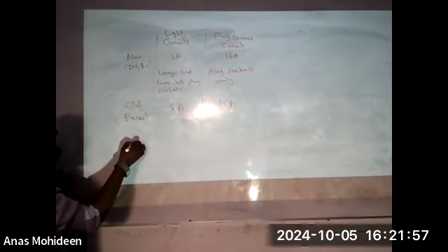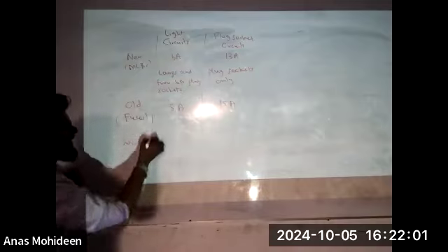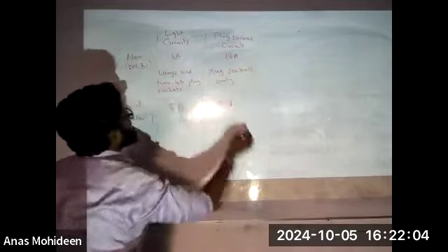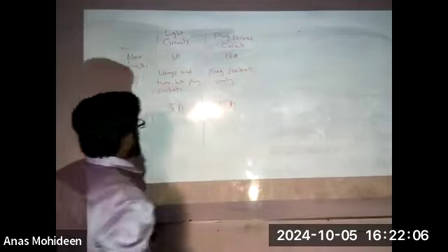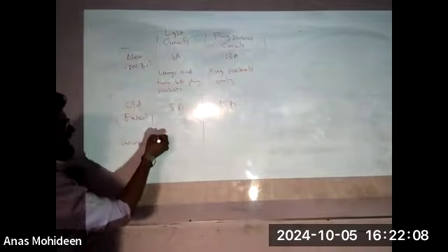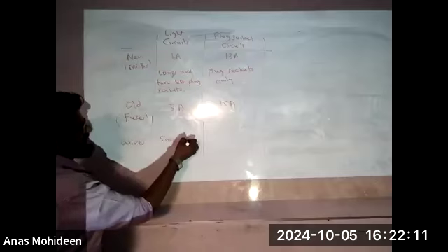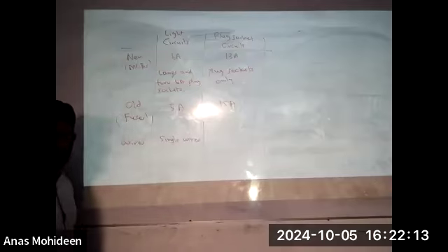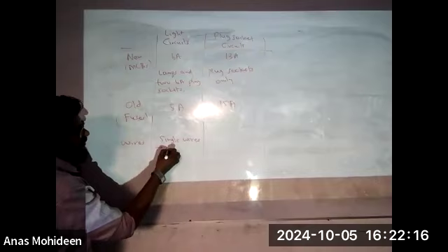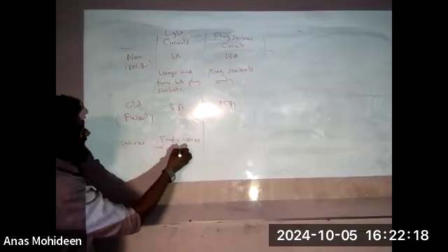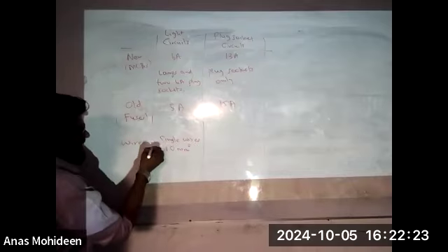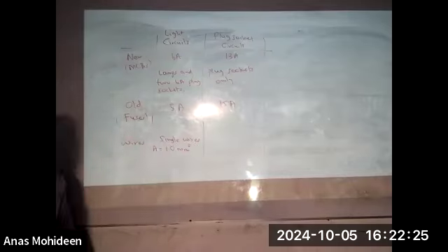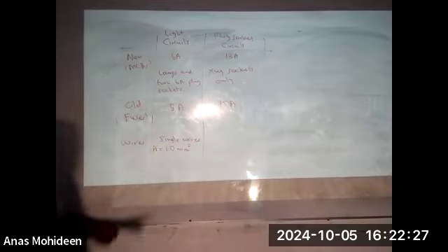And when we speak about the wires, the current flows through the wires only. In light circuits these wires are single wires, and these single wires are about 1.0 millimeter square cross-sectional area. The area is 1 square millimeter.